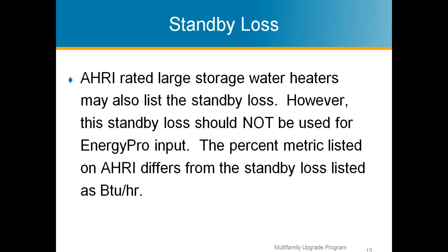HRI rated large storage water heaters, we also list the standby loss. However, this is not the standby loss you use in EnergyPro. The percent metric listed on the HRI differs from the standby loss listed as a BTU. So I'll explain that as we get into it. I'll show you what an HRI certificate looks like and where that's coming from in a minute here.